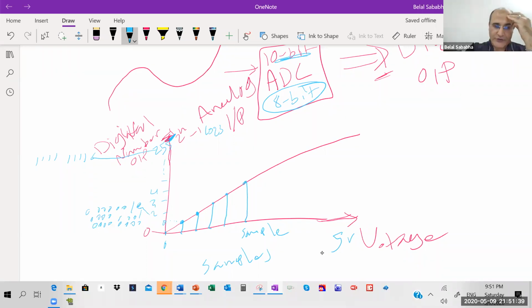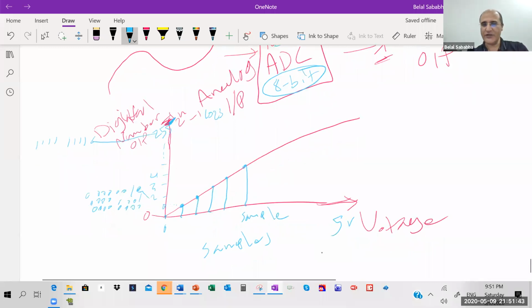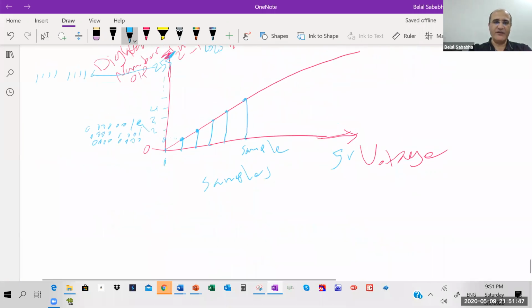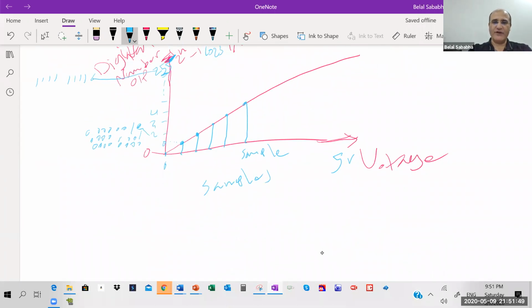The voltage you can recognize for reading is how much? If I read the 255, let's say our max is 5 volts, or 5,000 millivolts, then a 255 translates into 5,000 millivolts, right?